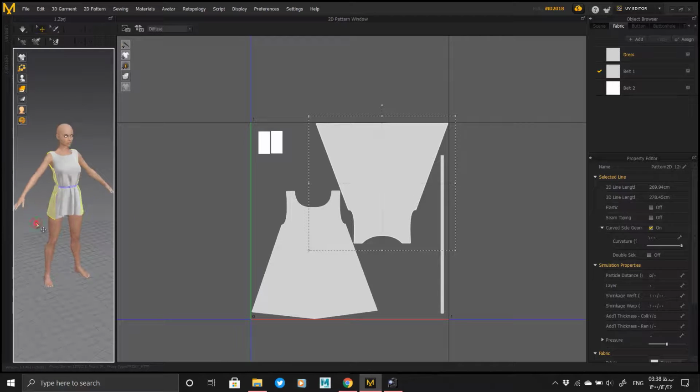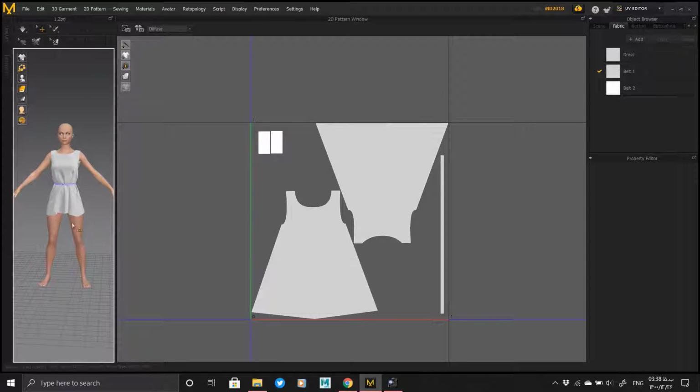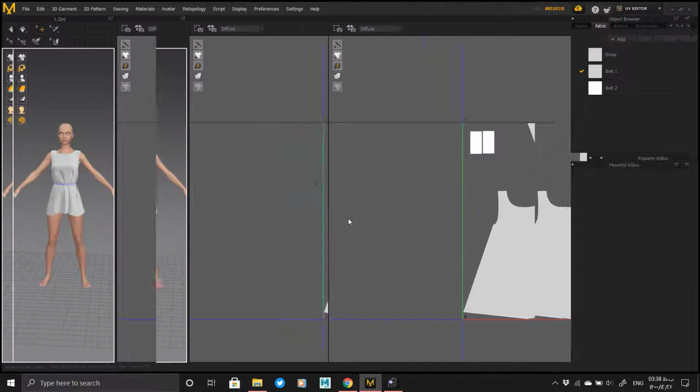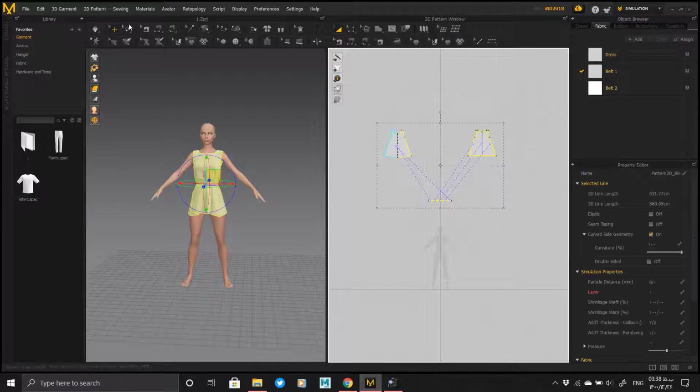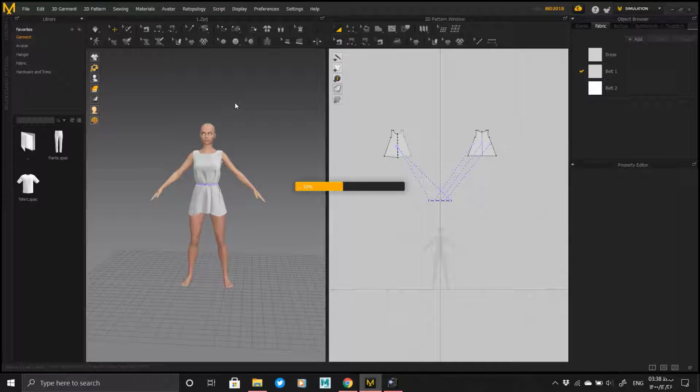The correct topology for other software is quadrilateral, and for the model to be standard, it is better to make the model topology quadrilateral. In the first case, you can select the model and select the Quadrangulate option, in the 3D Garment section, in the Edit and Context menu. This command allows the irregular topology to become quadrilateral.